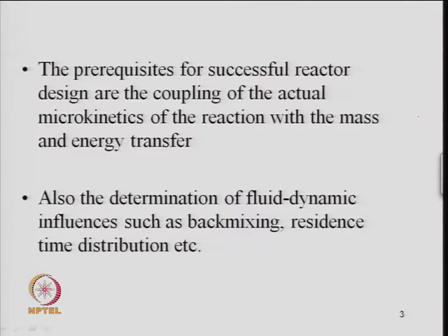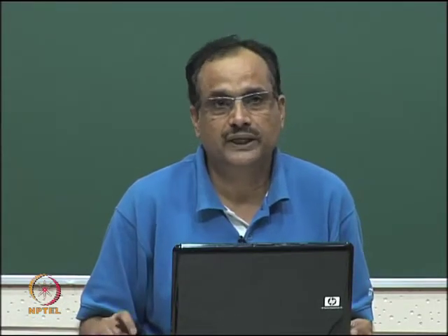And simultaneously the fluid dynamics also influence things like back mixing in the reactor, right. When you look at a plug flow reactor, we avoid that kind of back mixing, but in the case of an actual reactor we cannot avoid the back mixing. So, we need to find out the residence time distribution or some flow numbers like the Peclet number or dispersion number, which talk in terms of the degree of back mixing. That is a kind of axial dispersion or radial dispersion term, especially in the packed bed reactor, where the length to diameter ratio of the reactor is to be decided.